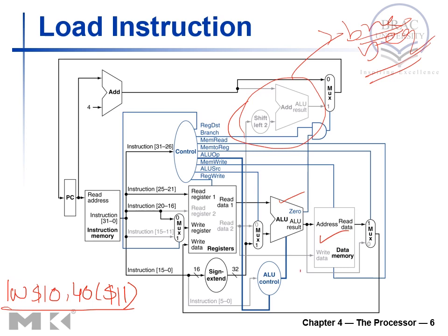That's why, see this link, this link is not active right now. Even though logically this link is not active, physically it is carrying some data, and that data is going to this port. But through this link, control is sending a signal that would only allow data coming through this port to get to the register file.